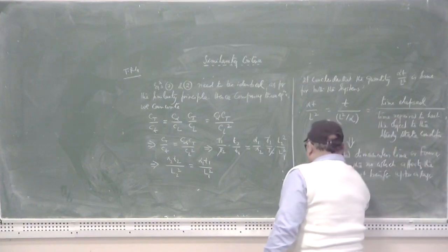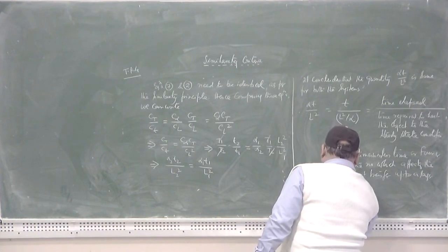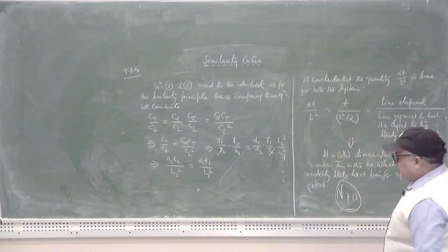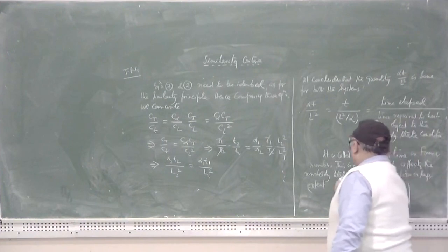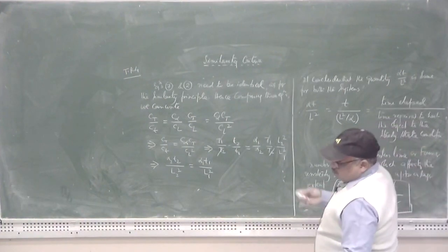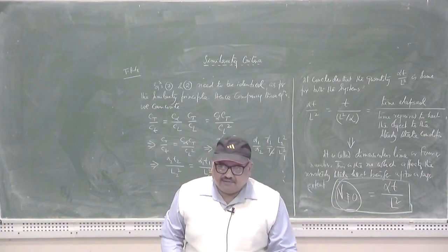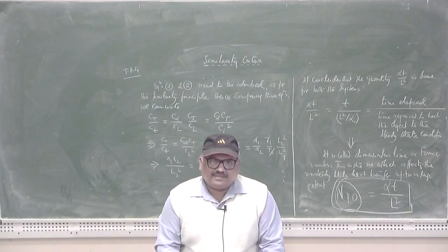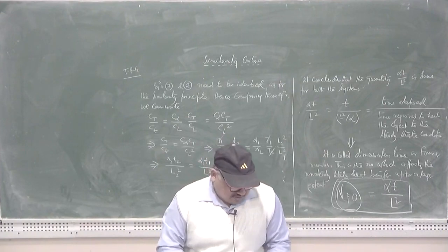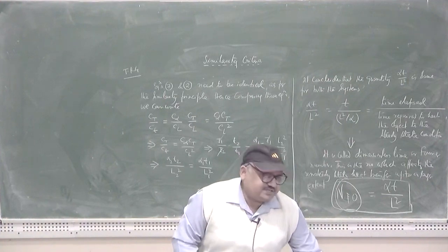So, by virtue of this dimensional analysis, we are able to know that the dimensionless number involved in the process is the Fourier number, or dimensionless time, defined as alpha t upon L squared. This is the beauty of dimensional and similarity analysis: arriving at the dimensionless number which is responsible for affecting the process going on in the two different systems.